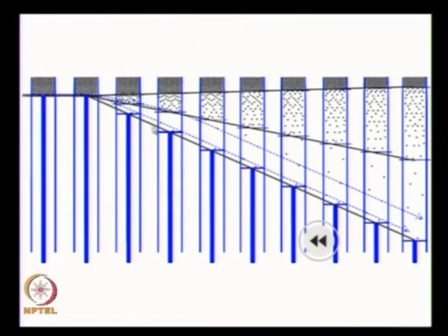We saw that a similar thing is happening in the compression wave, the oblique shock also, but I cannot show you what is happening inside a shock. Here it is a big region, I can show it to you very nicely. In the other case, the area between the streamlines will be very large before and after the oblique shock. If the streamlines turn, they will be much closer to each other. I cannot show you anything more than that. In here I can show that the stream tube is expanding during the expansion fan, after that it is staying constant cross section between them. This is one final thing I wanted to show before we jump into area variation.